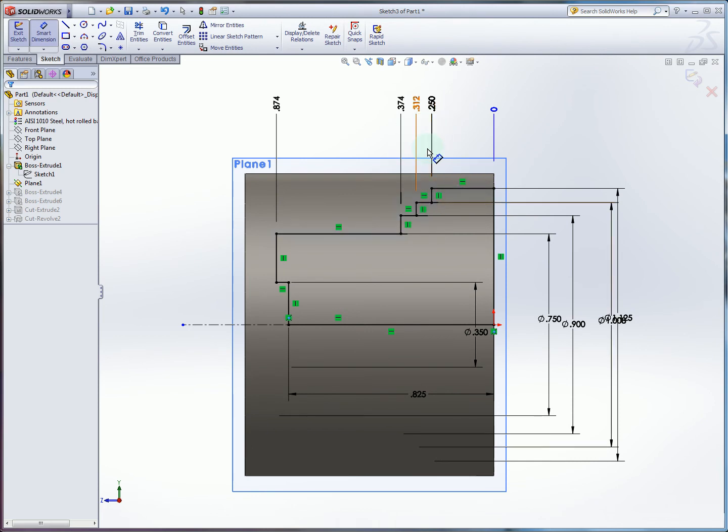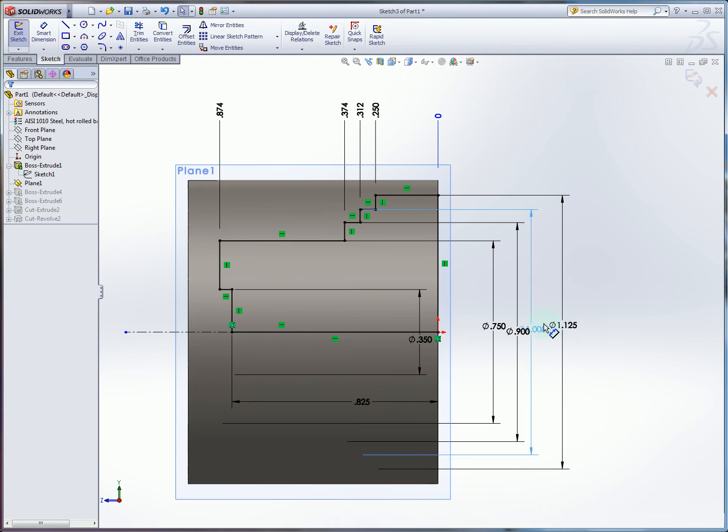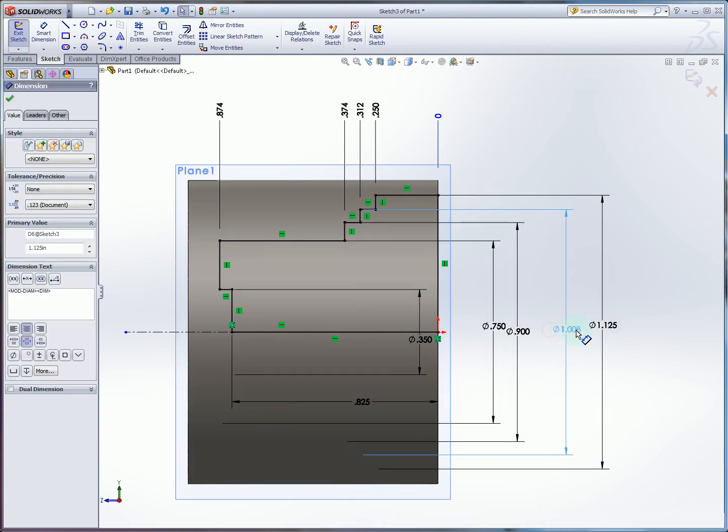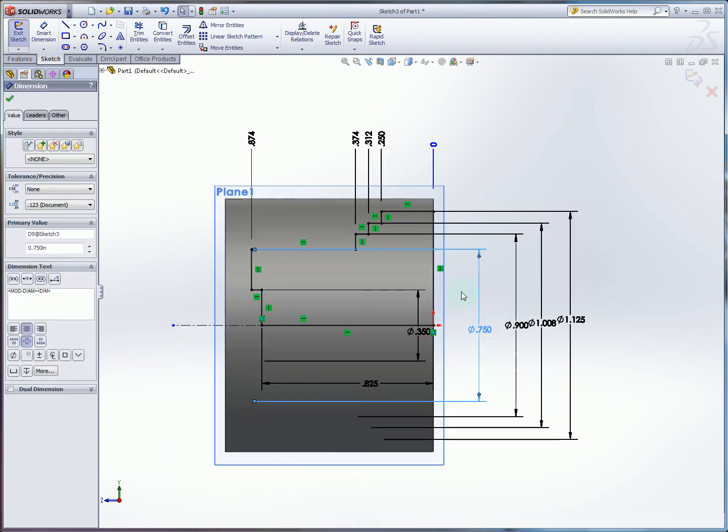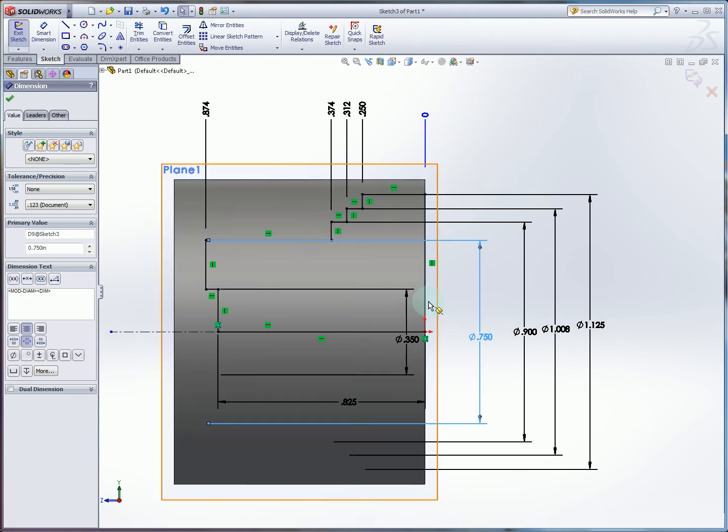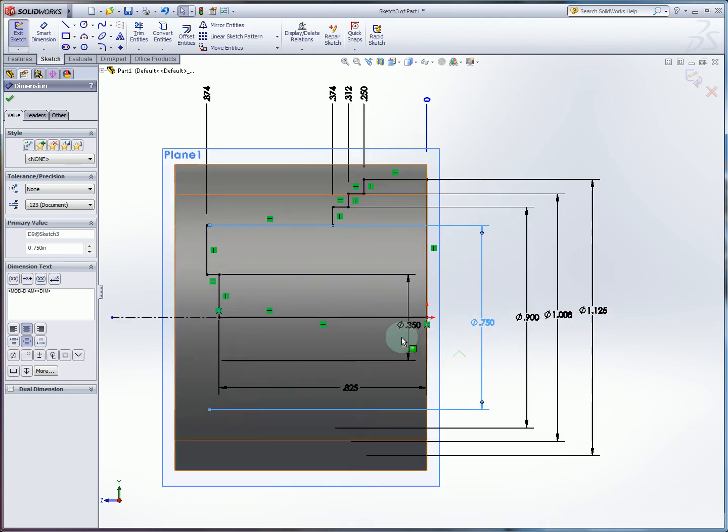And you can imagine that trying to fit arrowheads in all these little gaps might not be very conducive to easy reading. So another thing to look at, we mentioned cylindrical dimensions, and we can see that this feature is cylindrical, and I've only drawn half of it in the sketch, but I'm using diameter dimensions to show what each of these diameters are, and using this side view you can get a very clear idea that it's all concentric about this center line here.